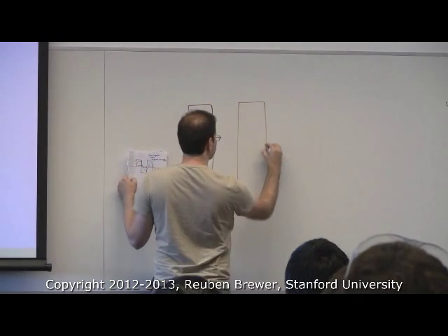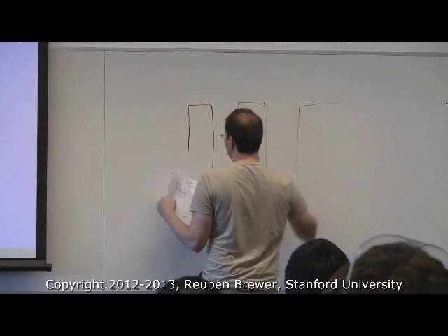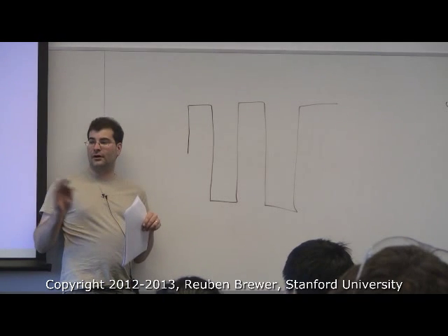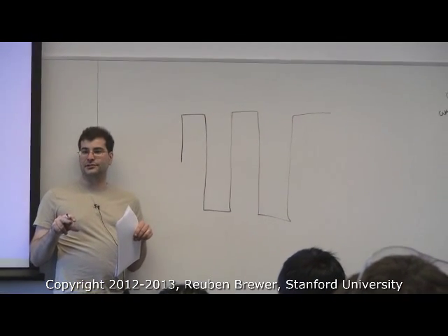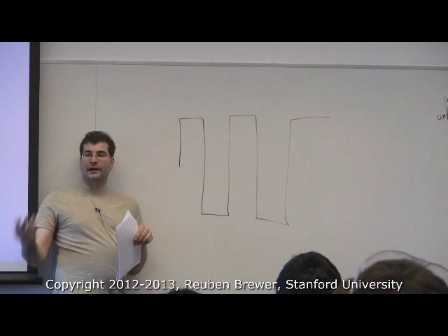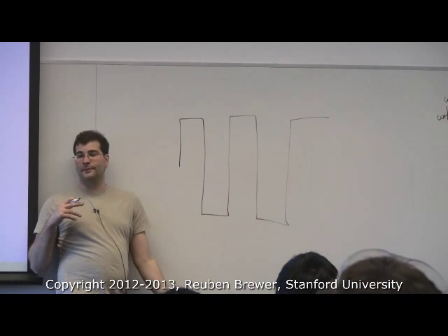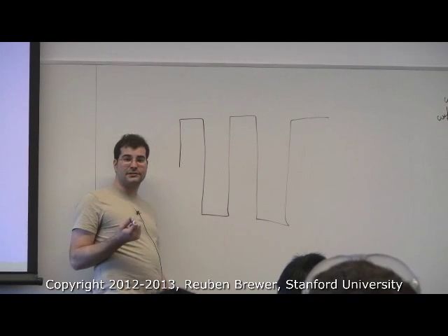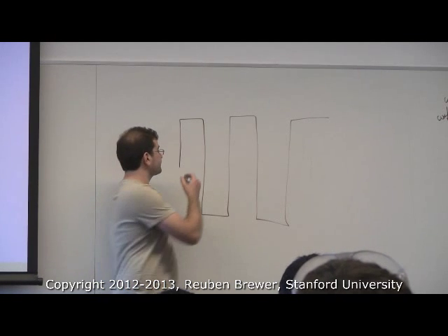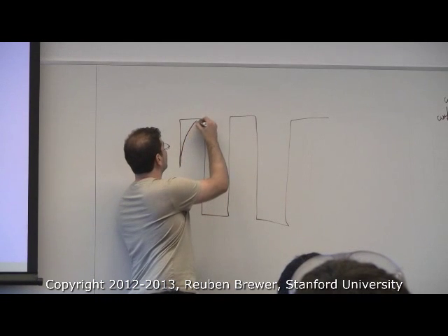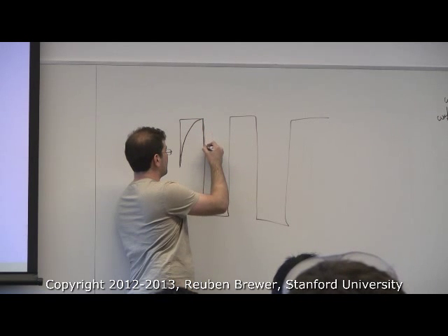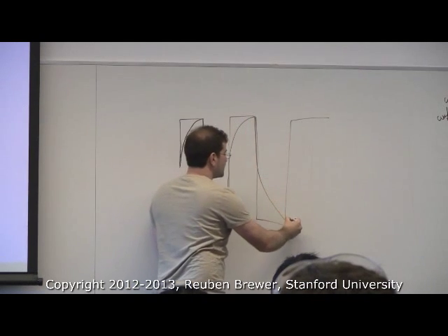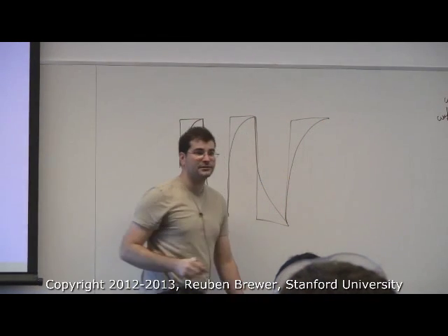Okay, so let's say we just have 50-50, and that's voltage. As we apply it, if the motor's off, there's no current in it, right? If we're at 0% duty cycle, there's no current. And when it's all the way on, we have as much current as we can have, right? But because of the transient from the inductance, we basically have a rise time, so it looks kind of like this. What I'm drawing here is the current, and again, that's because of the inductance.